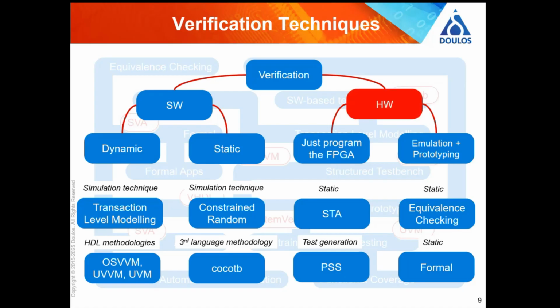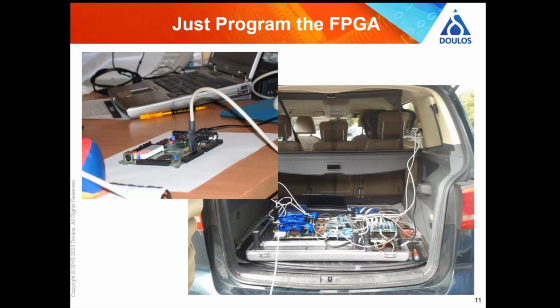And we're going to start with hardware, because particularly if you're designing an FPGA, one thing you could do is just program the FPGA. I would highly recommend you don't do that, because it takes quite a long time for the synthesis to run, for the FPGA software to lay out the FPGA, produce the bit stream, and then you get this piece of black plastic on a printed circuit board, and it's difficult to tell what's going on.